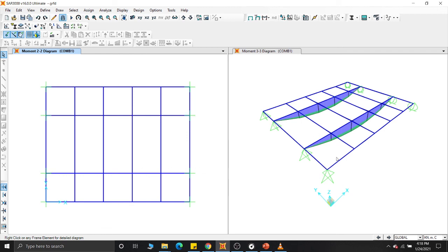I-girders, because this is a single cell box girder, because ideally what we have is a single section, a single box girder section. So whatever the bending moment that you have to consider in this box girder would be the addition of all four bending moments that will be acting on the two rectangular beams as well as the two I-girders. But when it comes to the torsional moment, it will be only the two I-girders that you consider here. So this is about how you model a box girder bridge, and hopefully I will try to